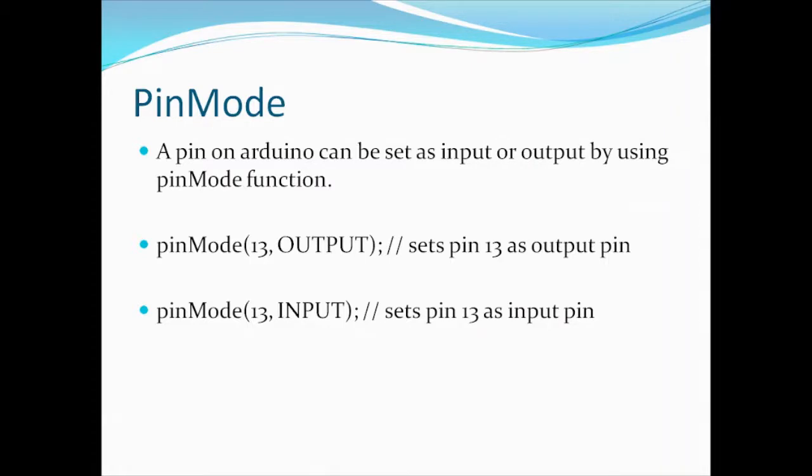So pinMode 13 OUTPUT suggests that pin 13 is used as an output pin, that is, you can connect pin 13 to an LED and expect the output to be generated. Next is pinMode 13 INPUT.